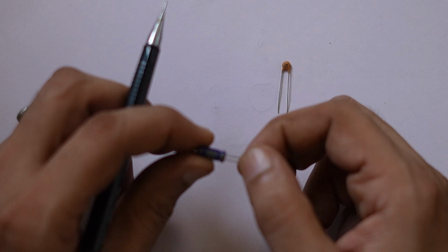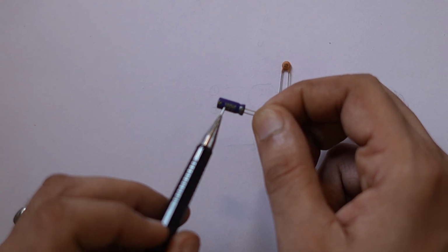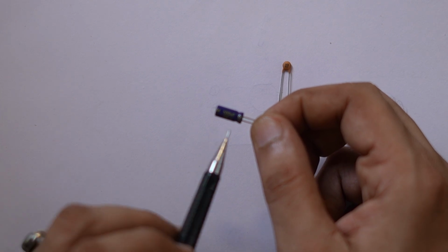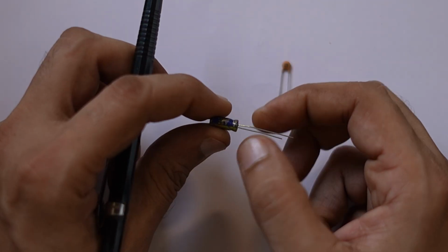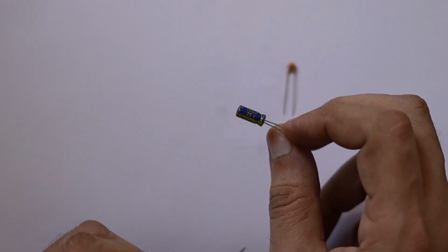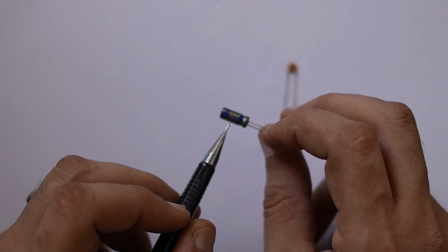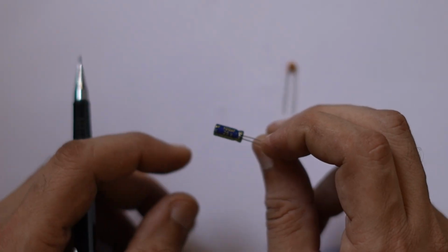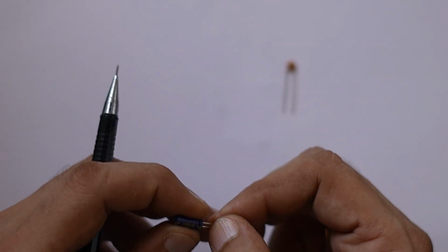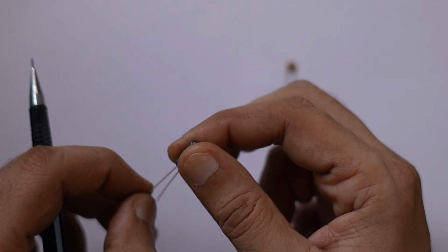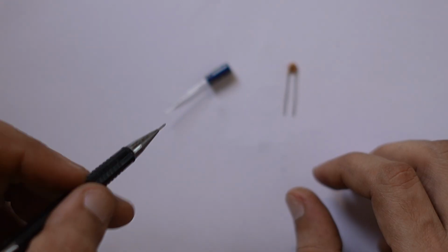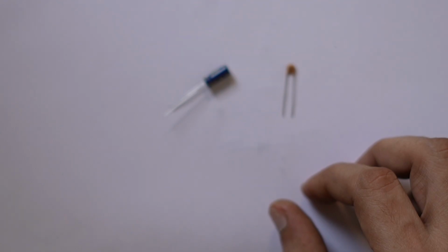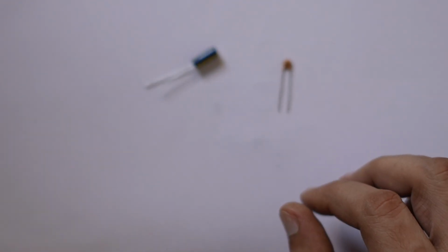One is what is its capacitance. In this case, this one is 100 microfarads. So 1000 microfarad will be much larger than this, and its voltage. This one is 25 volts, but a similar 100 microfarad 100 volt capacitor might be slightly larger. So these can actually act like a sort of a battery. Like I said, when you apply voltage to it, it will charge up, and then when you remove the voltage, it will slowly discharge. It will be like for a couple of milliseconds, depending on the size, up to a couple of seconds if it's a very large capacitor.